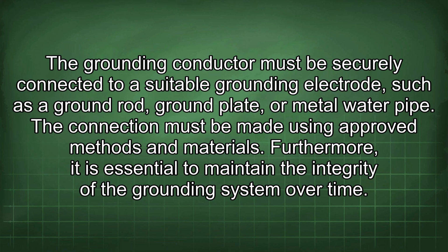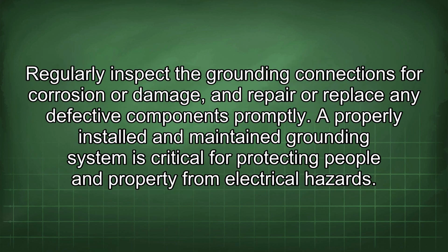Furthermore, it is essential to maintain the integrity of the grounding system over time. Regularly inspect the grounding connections for corrosion or damage, and repair or replace any defective components promptly. A properly installed and maintained grounding system is critical for protecting people and property from electrical hazards.